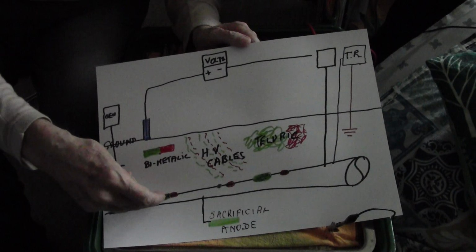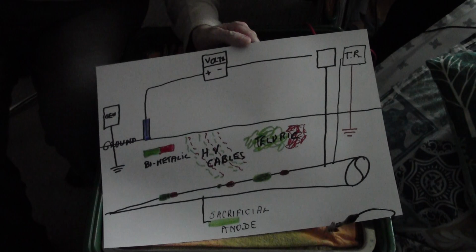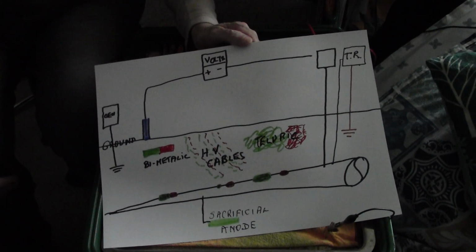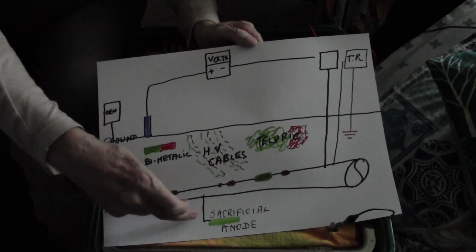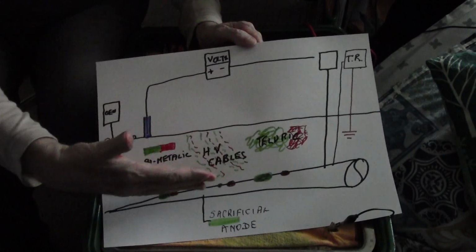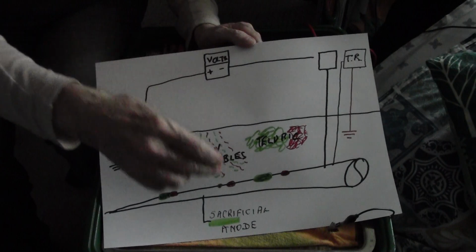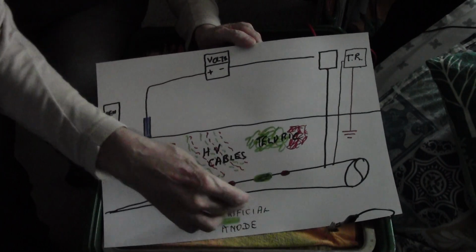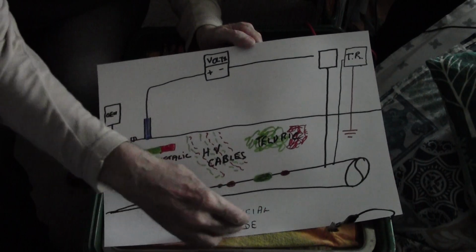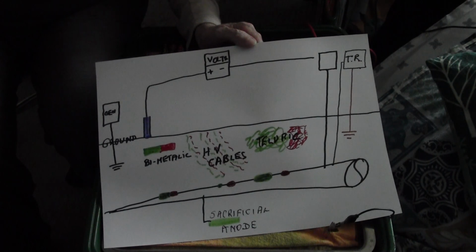Some of them will have the anode and cathode combined in one coating fault. And then, of course, we have sacrificial anodes buried, and they will affect the whole of the pipe potential. But also, if you put your half cell anywhere near these, you will obviously get the effect on the ground, which will be included in the measuring circuit.